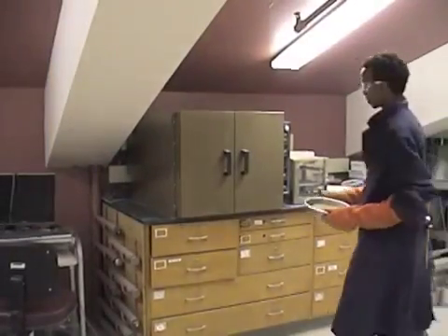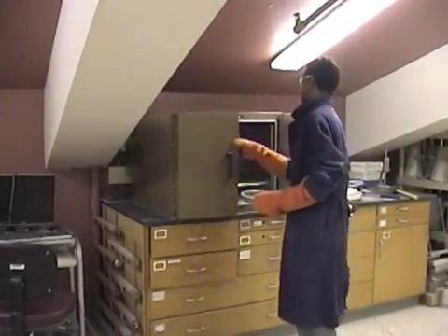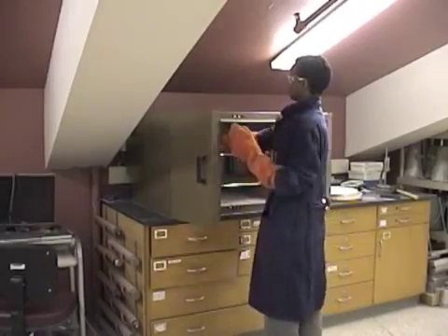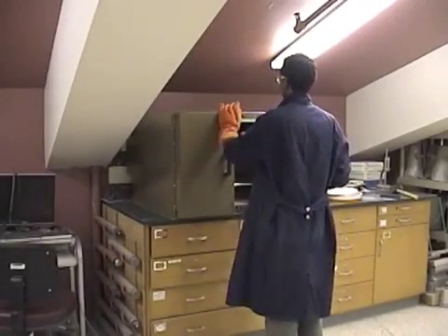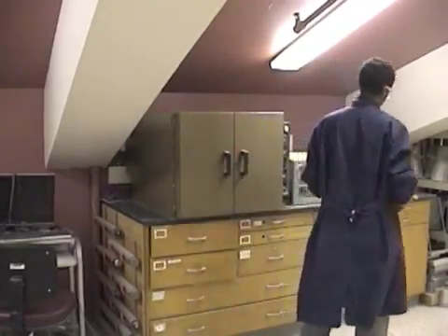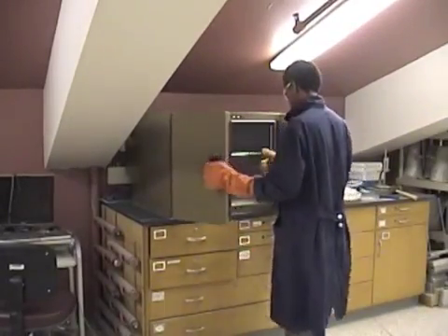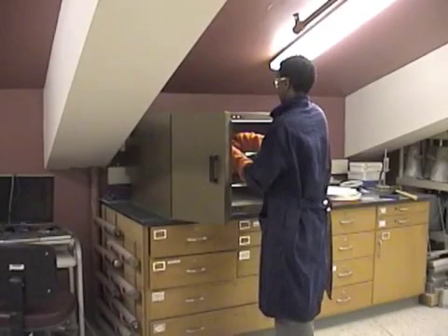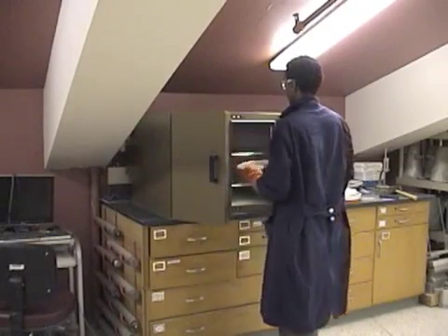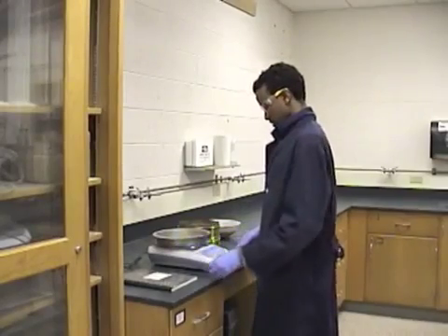We dry our sample by placing it in an oven that has a temperature of 110 plus or minus 5 degrees Celsius. Once we remove our sample from the oven, we want to allow it to cool for 1 plus or minus 0.5 hours, and again record the mass of the now dry sample.